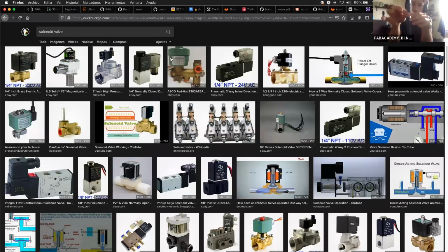Inside here you have a metallic needle. I will show you a picture in a second, but with very high pressure, at 2000 bars of fuel pressure, the needle gets activated or not activated by a coil that is in this big part in here. You can see here the two electrodes that will activate the coil, and here is the point where the fuel goes inside. This whole thing is basically a solenoid injector, used to put fuel inside the chamber of a combustion engine.